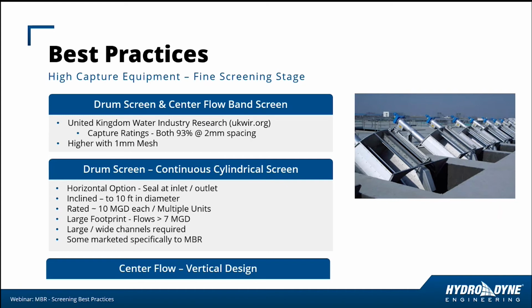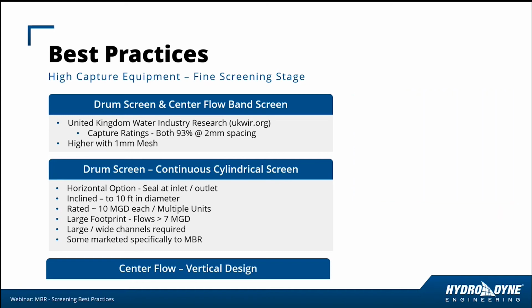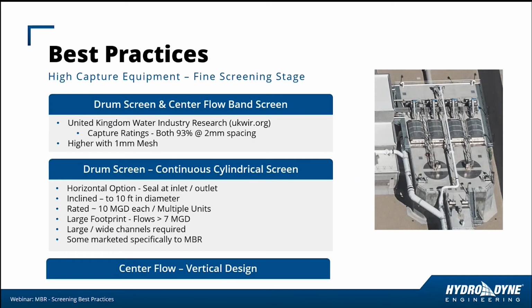Some drum screens are marketed specifically to MBR, so they're designed specifically for membrane processes and have the spacing needed to accommodate that. Moving on to the next screening design that is approved for membrane treatment. There's another example of a drum screen setup.